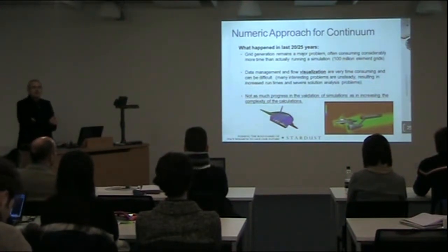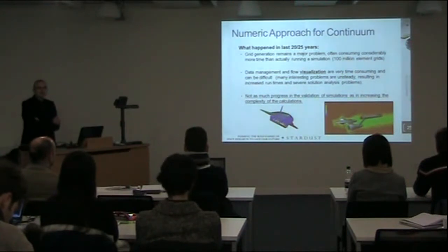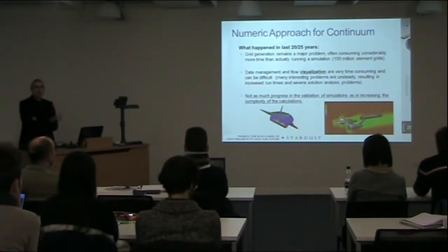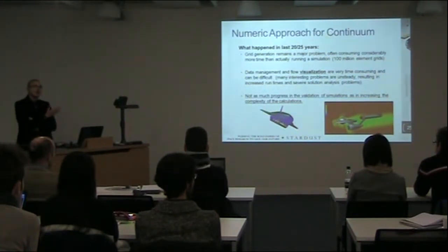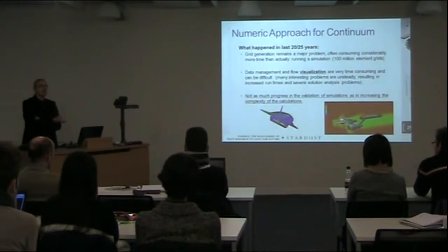So in that case, you can use unstructured meshes instead of structured ones, because unstructured meshes are easier to build, but they also pose some problems in numerical terms. You cannot really compute fluxes of quantities easily, or precisely, let's say, in unstructured meshes.